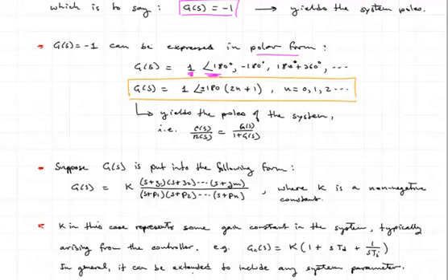So wherever there is a pole, at that value of s, G(s) should have a magnitude of 1 and an angle of 180, or some multiple of 180 plus or minus n times 360. Okay, so anything that lands us pointing on the negative real axis. So we can write that as having an angle of plus or minus 180 times (2n plus 1), where n is 0, 1, 2, 3, etc.